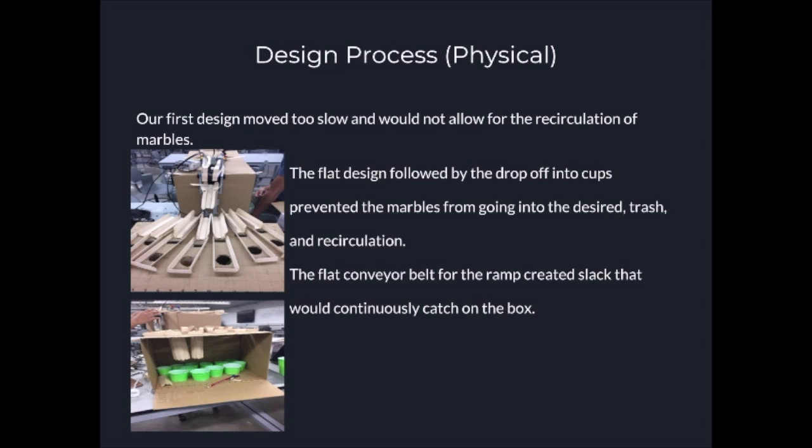The box that we had to sort the size of the marbles was also a problem, as sometimes our marbles would fall into the wrong hole before they could reach the proper sizing hole. And then also our conveyor belt being flat, it would also snag on the box itself with the pegs, or it would catch in its own design and marbles would fall off.